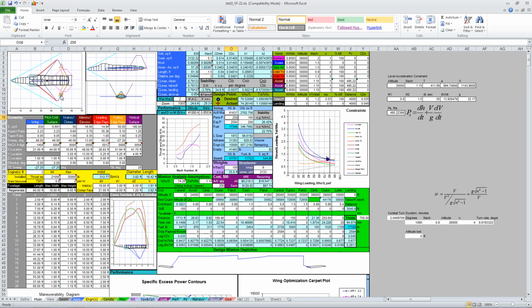Alright, now something funny happened here on the wing. The ailerons are kind of hanging off now. And I need to do something with those ailerons anyhow, because you notice the aileron column is labeled ailerons/elevons. And we want to turn those things into elevons since we no longer have a pitch control surface. So the way we do that is we just put the ailerons right on top of the flaps. And we do that just by referencing the cells.